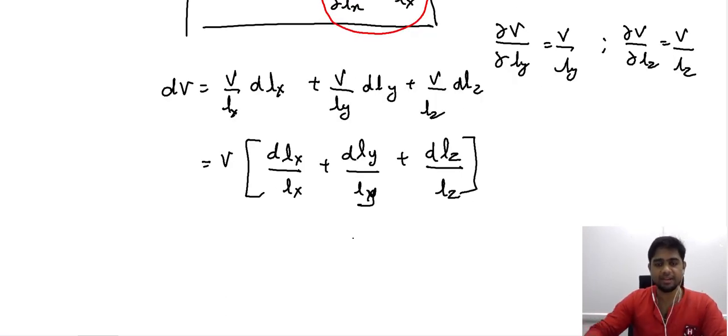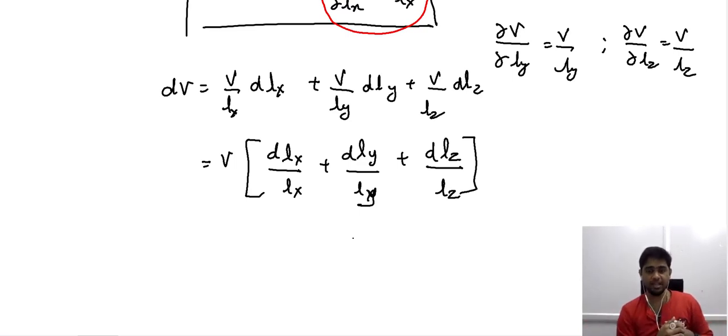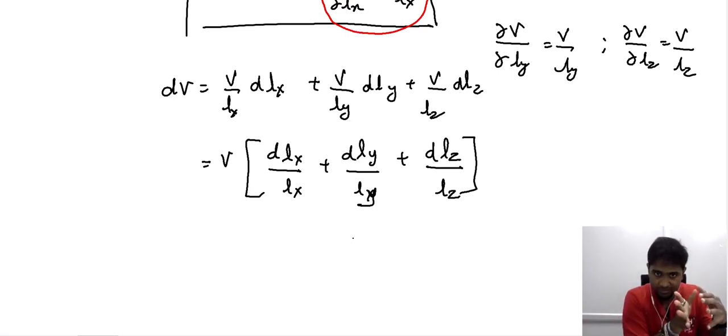So what we have then ended up with is three sets of terms, and each of these terms indicates the change in the dimension because of the loading that we have imposed along the specific direction, and it is the ratio of this change in the dimension to the original dimension along the same direction. So therefore this ratio is nothing but the strain.